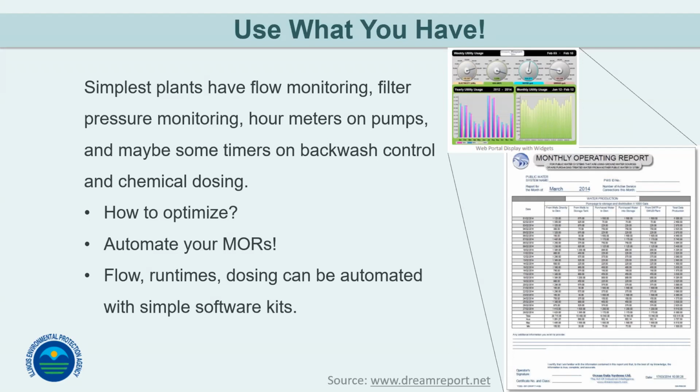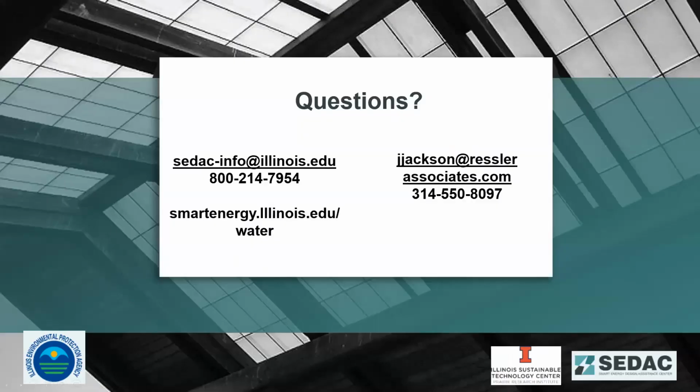And then you can put together a trend and know how things are going to run, and motors on VFDs will ramp up and down to meet that need to be the most efficient as it goes forward. So anytime you can put some type of process instrument in place and run it back to your SCADA for control, I love it. I think it's so efficient and so helpful for the operators. Especially nowadays, you can go ahead and get those and put them on your cell phone as well, so you can see them on a tablet or see it remotely, and that's always a lot of fun as well.